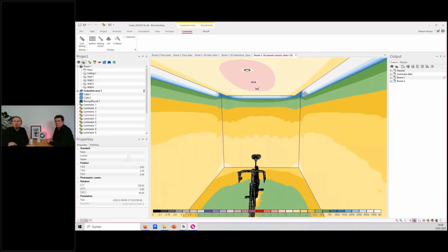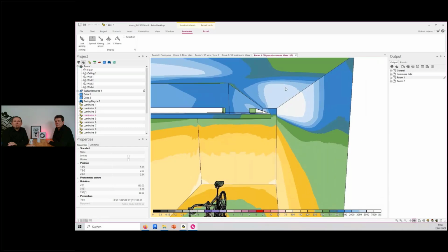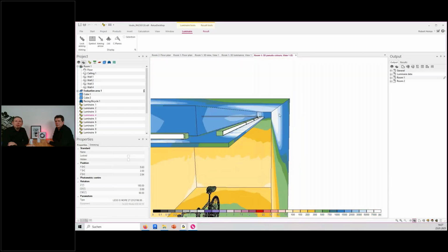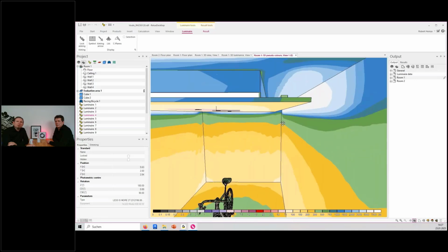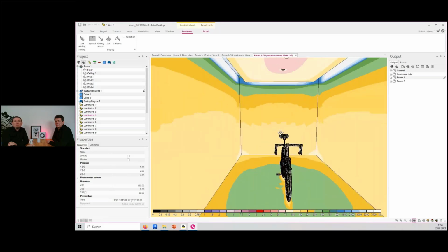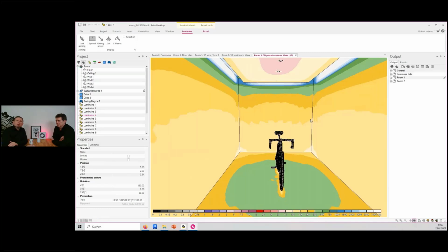You need a lot of energy, a lot of luminous flux, in order to make this work with the fraction of reflection on the wall, and it also needs to be really good reflecting material. So white paint, the best white paint you can find on the market, and then you have this nice diffuse light output from a corner. You do not see the luminaire. You have a perfect glare-free, shadow-free, but maybe a bit boring light because there's not any focus in it.